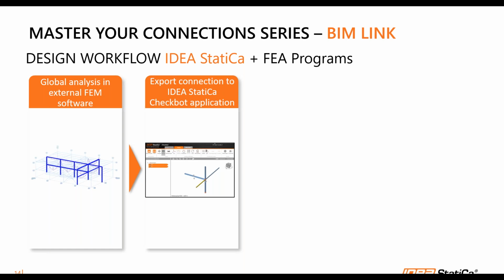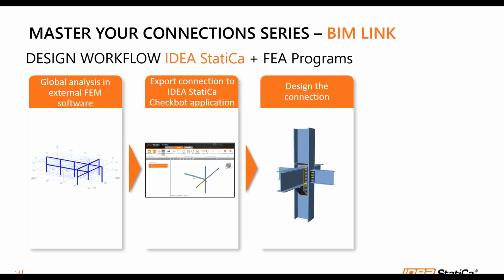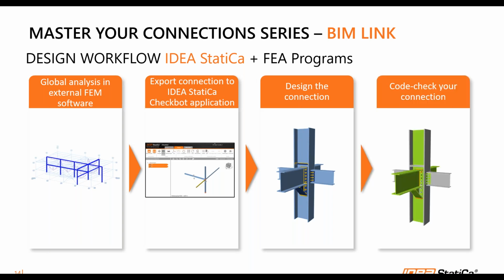So you will actually save some time doing manual inputs in your design application, because imagine how much time you would spend doing all that. For example, you have 100 combinations. That's quite a lot. So once you capture that, all you have to do is export to the connection application, put in some manufacturing operations, and then run the code checks. So that's the basic workflow of using the FEA programs with IDEA StatiCa.